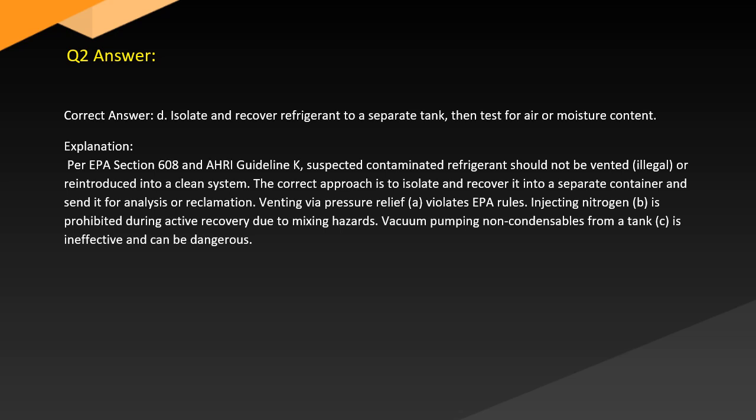Injecting nitrogen (B) is prohibited during active recovery due to mixing hazards. Vacuum pumping non-condensables from a tank (C) is ineffective and can be dangerous.